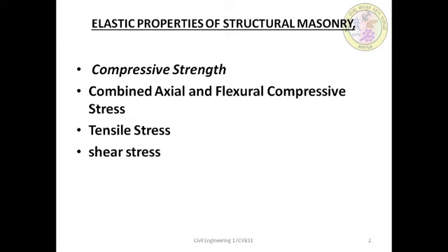The prediction of the behavior of masonry assemblages on the basis of its constituent materials is too complex. Hence, the strength and elastic properties of the integral materials are determined by making wall specimens and testing them under vertical and cyclic lateral loading.